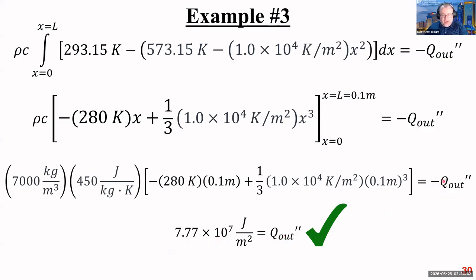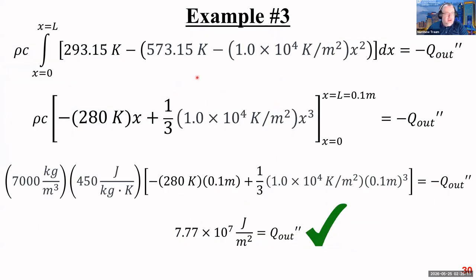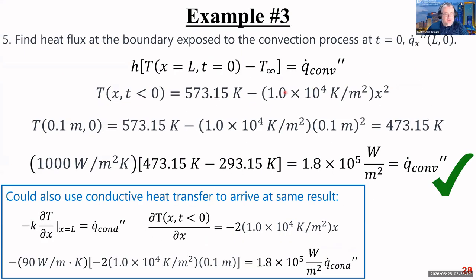So let me just point out, because again, we had some convection, and convection is weird, because you can swap things around inadvertently. I have convection heat transfer leaving my system, and so leaving the system is a heat flux out, and so this negative sign comes from my first law treatment of that thermal energy leaving the system. I didn't actually, at least in this stage, have to solve for a convective value, but I did in the previous step.